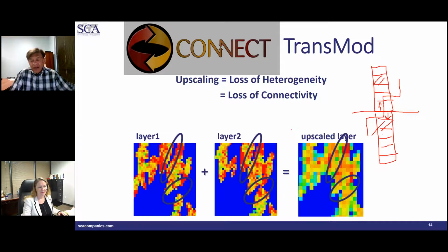which is the fractures explicitly defined, and you have a fracture permeability as well as the matrix permeability, is that we use the fracture permeability to calculate the speed at which the pressure wave travels, because we assume that that's the higher permeability and that's what determines how the fluid is going to move. But you have the option of dual porosity model, so you can utilize that dual porosity model and run the 1D model just like your 3D model will run.